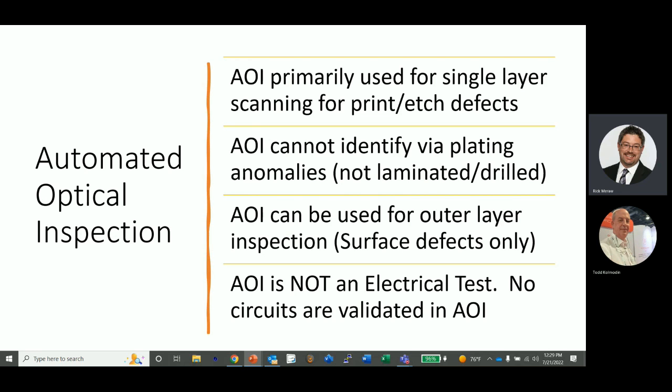When you print and etch, the old style of making a circuit board, the copper itself is very uniform. You may have some etching tolerances on the edges of the tracks, and different kinds of etching may cause some differences, but relatively the copper looks the same.